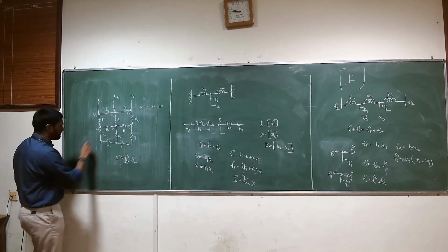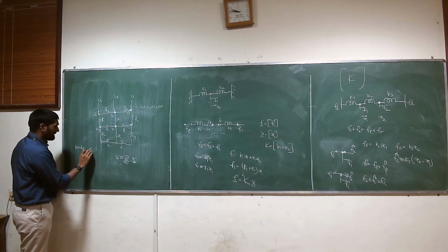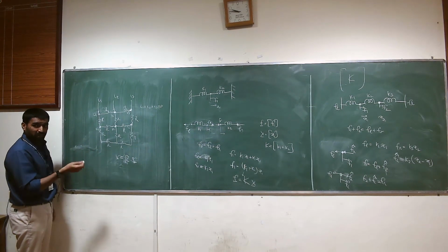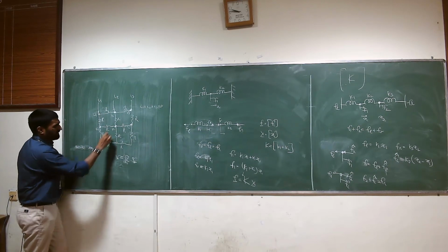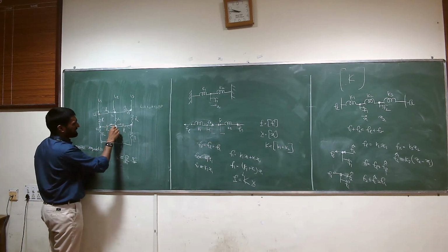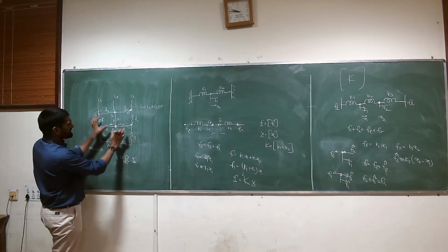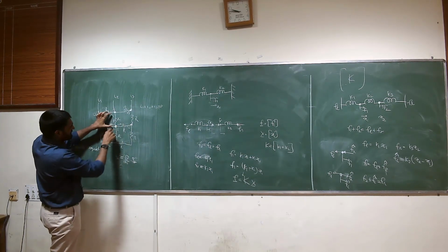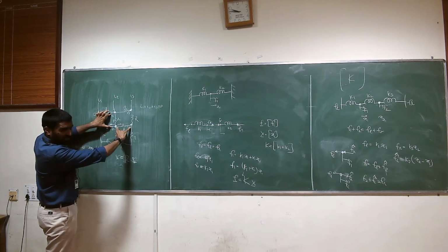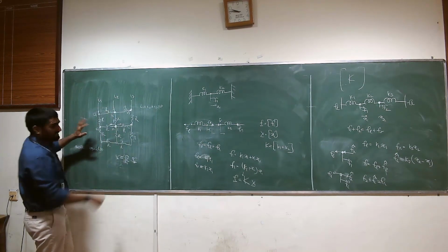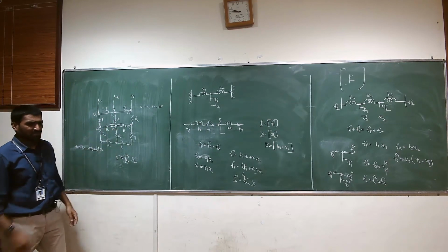And for this, you simply use Kirchhoff's loop law, and then another one is the node equation, where if you have this node, the sum of all the currents entering or leaving this node is 0. And the current here relates these two voltages and the resistance of the path. Similarly, the current here, here, and here. And if you write that, you'll get an expression in terms of the voltages of the nodes. That's how you do this.